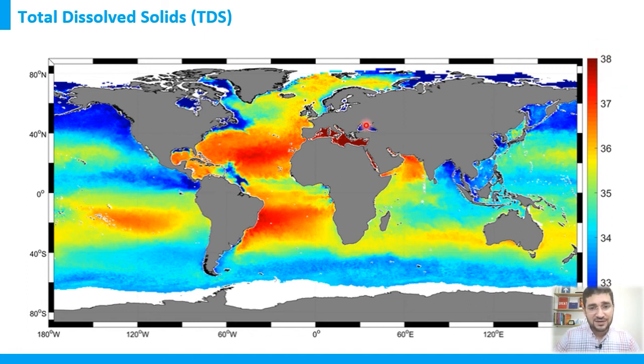And you can see here, for example, in these Arab countries close to Saudi Arabia, the Emirates, Qatar, Oman, and those countries, we have red color. That means we have very high TDS, because in this area of the world, even on the North Africa side, we have many desalination plants. That means brine water is going back to the sea, and most of the seas here are a bit restricted, so there is not much flow of water, so the salt level increases with evaporation.